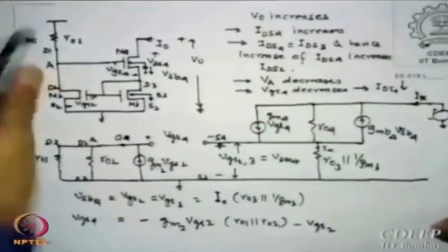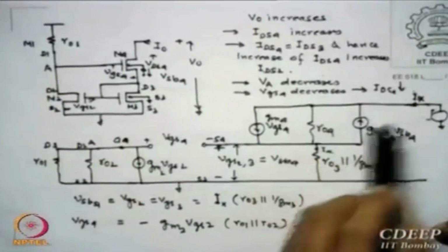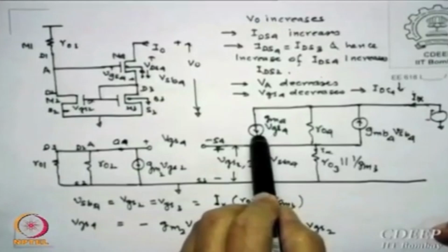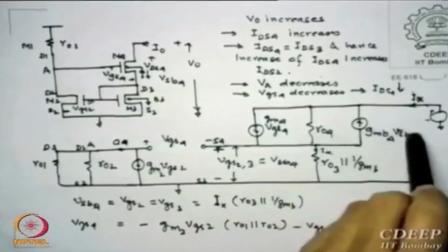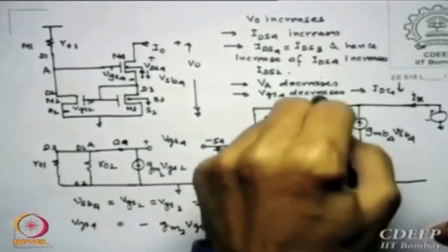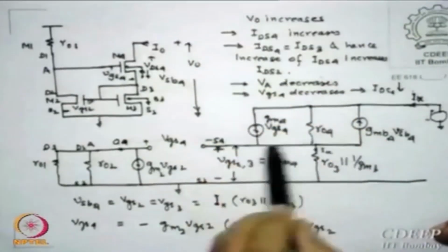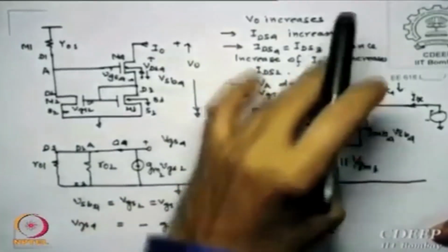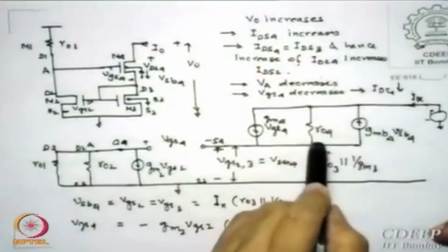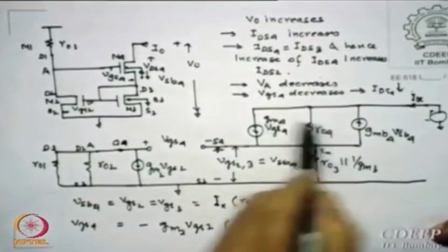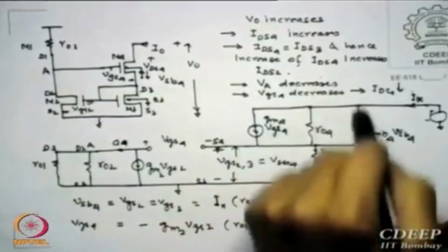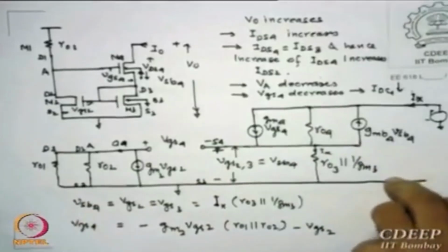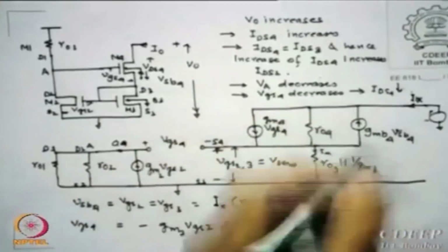Okay, see the circuit, this Ix is divided into 3 currents, is that correct? gm VGS4 minus gmb VSB4, plus Vx minus VGS2 or VSB4 divided by ro. This voltage minus this voltage divided by R4, this current source and the opposite current source, this is the net current which is Ix, is that okay?